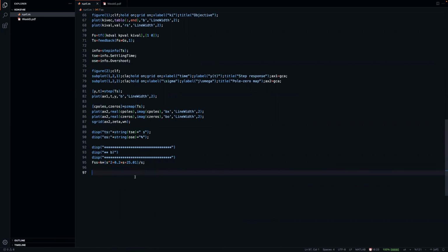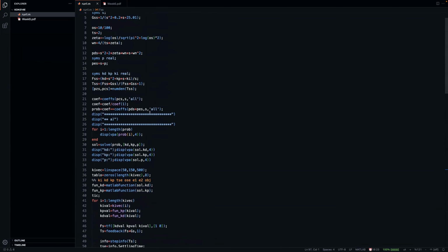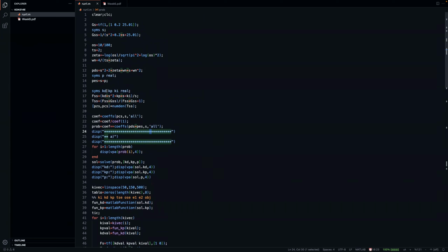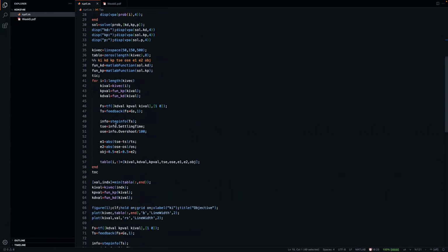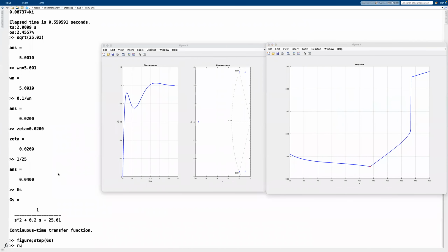Now you can see when you know the location of the zeros, and since you will know that you're adding a pole at the origin, you are done with the dynamic part, which only leaves us with the proportional-type controller part of our whole structure here. So the only unknown is going to be K, which is going to be a real value. And well, we can look at the closed loop here, like this. And it would immediately show us something that we already know.